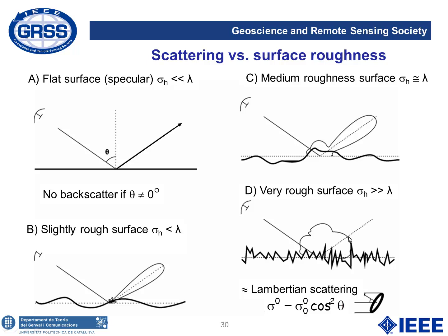We have lost this privileged specular direction, and this is called a Lambertian scattering situation, where the radar reflectivity does not depend very much on the angle of incidence. It depends a bit because of the effective area which is observed depending on the angle, and this is modeled by this cosine square of lambda, but it's not very directional.